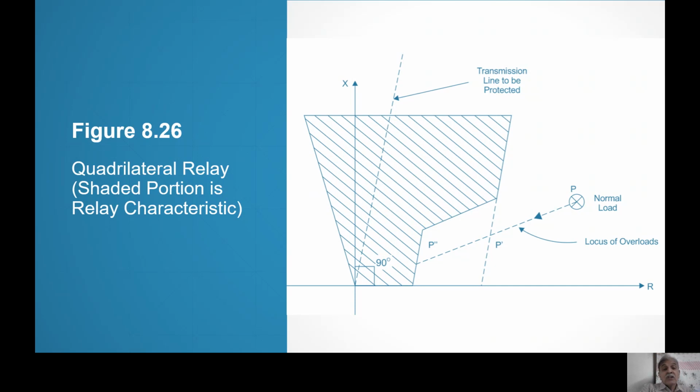And because our system is expanding like anything, whole India is connected now. Kashmir can feed power to Ahmedabad. When such a thing is there, that is very good. You will like it, that if Gujarat has no power, Kashmir will feed. But the problem is when there is a fault in Assam, the complete nation will feed that fault, and therefore that fault current will be very high. Fault current is high to the tune of 30,000 MVA or so.